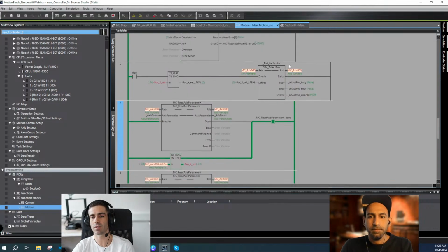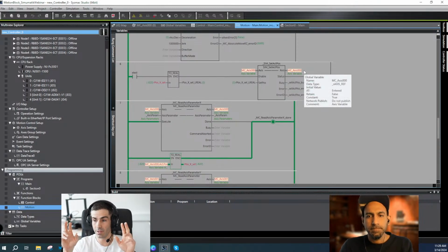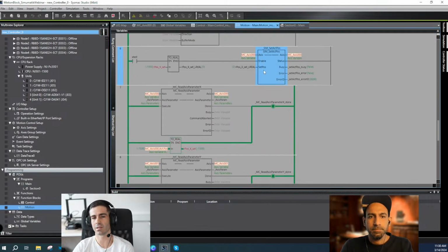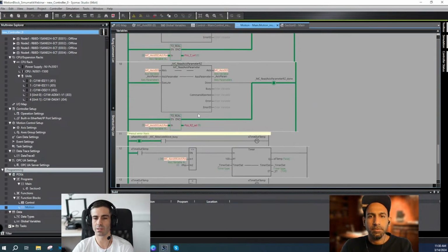actual position. For that, we got the idea from Omron, the R&D department, that we could use this simulation set actual position. We haven't experimented much with it or made it work yet. But I guess we need to disable the ideal axis calculation, and force the encoder position or the actual position with this function. So we will be doing these experiments. I think it can add extra value to users working with Omron, so they can close the loop.